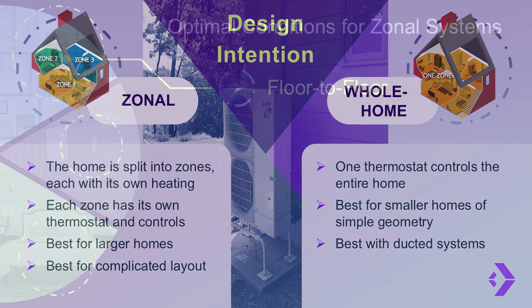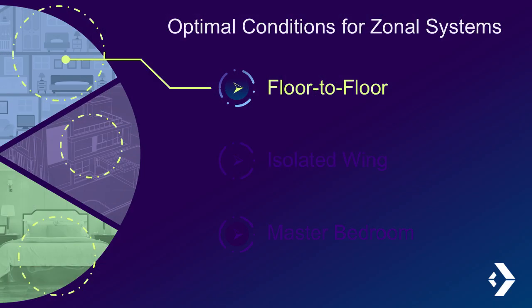customer's needs. Zoning with heat pumps is so much easier than it is for other system types that we can avoid the challenges and costs of whole home distribution common to central furnaces and boilers. The most obvious zoning is to separate each floor as its own zone and remove the effort to blow air or pump water between floors.